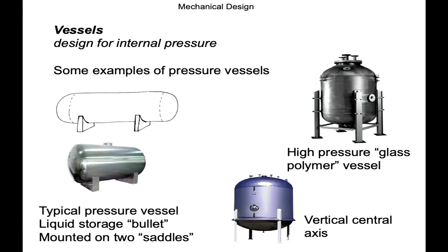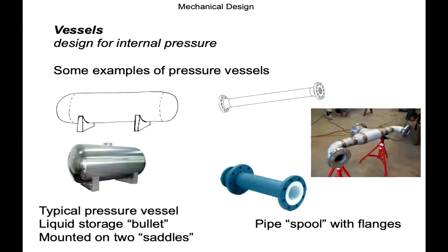One more thing to note on this, I said domes. For a pressurised system, you would never put a flat plate on the end. The flat plate would want to bend, distort, bow out, and you put extraordinary stresses on that region of discontinuity between the cylinder and the end plate. That's why there's this doming. The stress levels in that interface, or in that discontinuity zone, are high enough as they are. I'll talk about that later. So you can see, it's just a norm that people make use of.